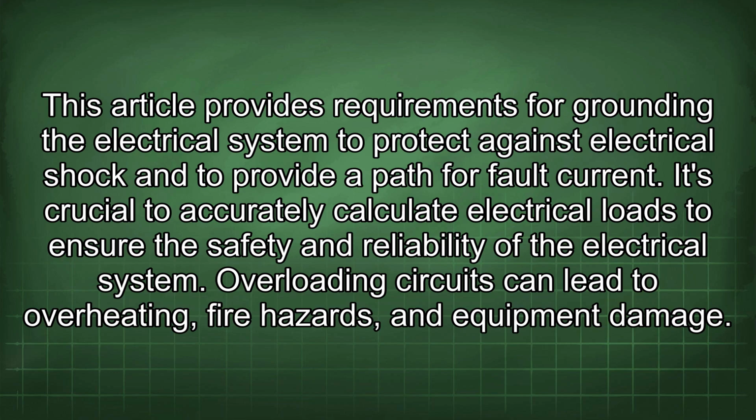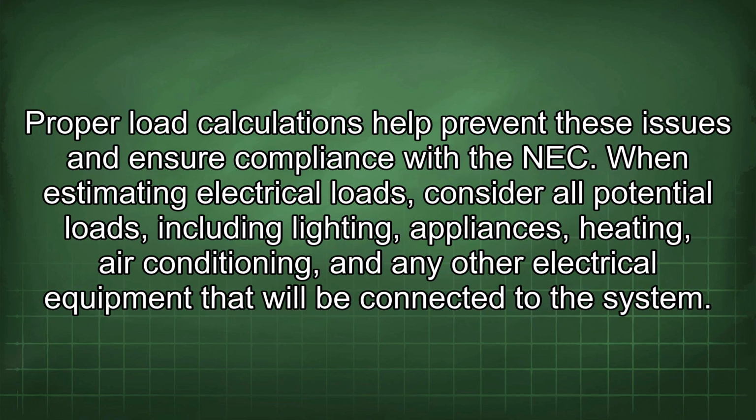It's crucial to accurately calculate electrical loads to ensure the safety and reliability of the electrical system. Overloading circuits can lead to overheating, fire hazards, and equipment damage. Proper load calculations help prevent these issues and ensure compliance with the NEC. When estimating electrical loads, consider all potential loads, including lighting, appliances, heating, air conditioning, and any other electrical equipment that will be connected to the system.